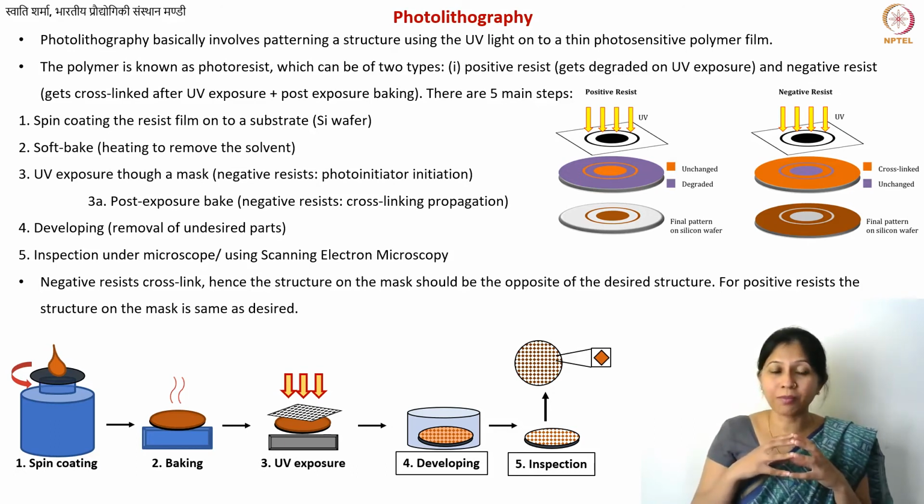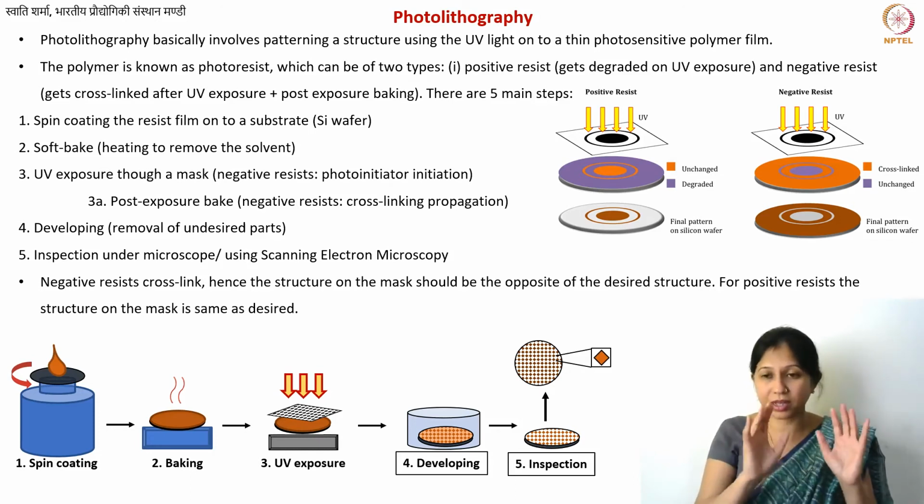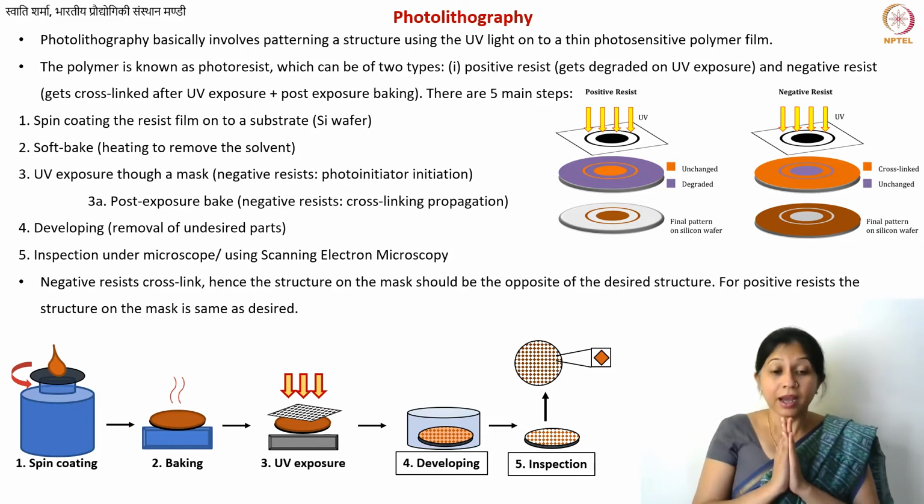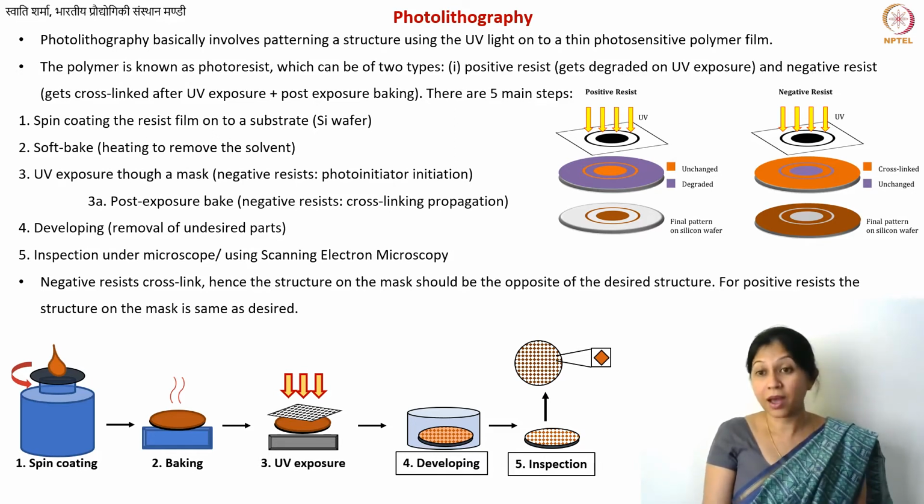Okay, so now what is the next step? You have a photoresist, you perform photolithography, you get some microscale structures, and now you take your entire silicon wafer or the pieces, put it inside the furnace, and heat it at 900. Now, why 900? There is one more important thing. Why don't we go to 3000 degrees? Why can't we make better carbon? We know that if we increase the temperature, it will increase the cost of the overall process. That is true. It's energy consuming and so on.